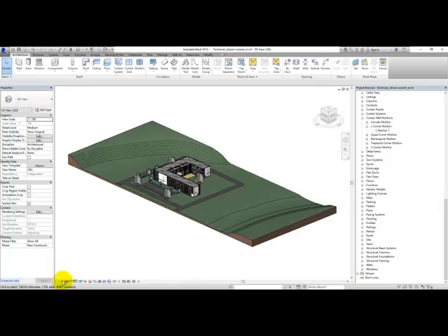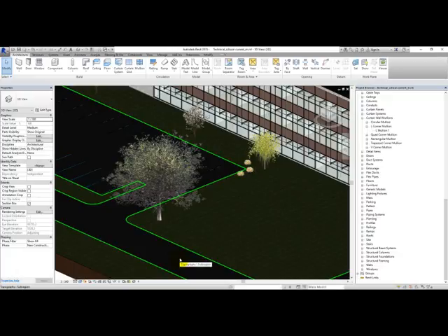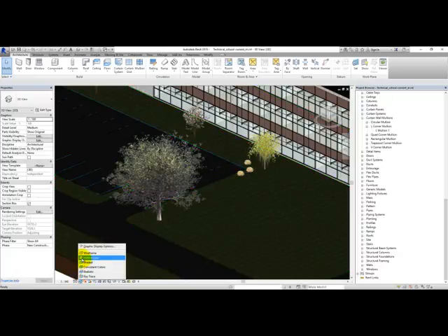So down here you see you've got your scale, so you can set the view to a scale. You've got detail, so you can set the detail level to 3 levels: coarse, medium and fine, and again we'll get into that in later videos. You've got your visual styles, so you can go realistic. Just let that quickly go through. So this is what it will look like in realistic terms as soon as it's done it. And if you see them trees have changed, if I zoom in a touch, so you can set them to various different ones.